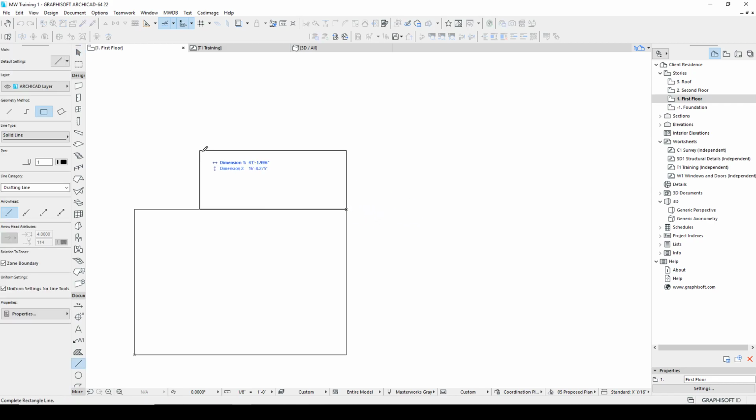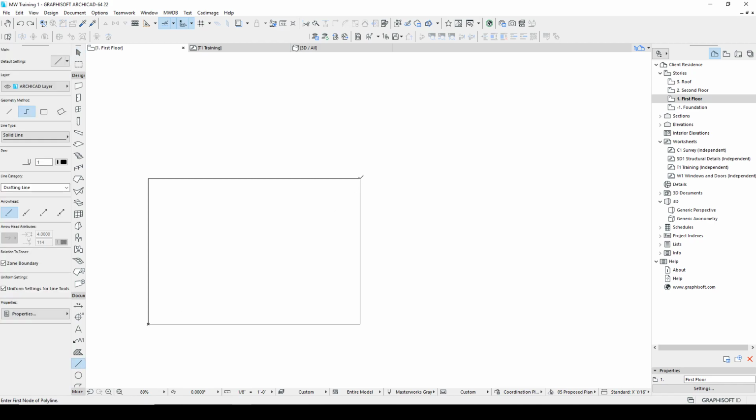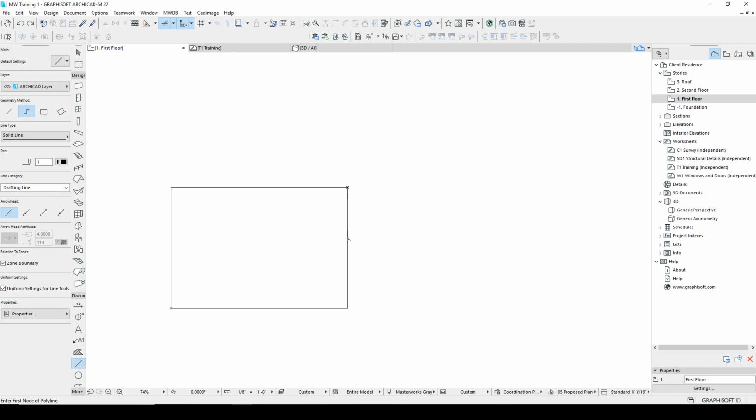Normally we draw a line. Let's hit G and we go X10, Y10. Draw a line, and then we'd start tracing our shape. And that's fine. But then I have to go back, hold Shift and delete this. The alternative method, and learn how to use this, folks. This one's cool. Go to a line, hit Shift Alt, Shift Alt. And notice how it moves my origin. And I can move it anywhere I want. And then when I key in values, X10, Y10, it's from that point.